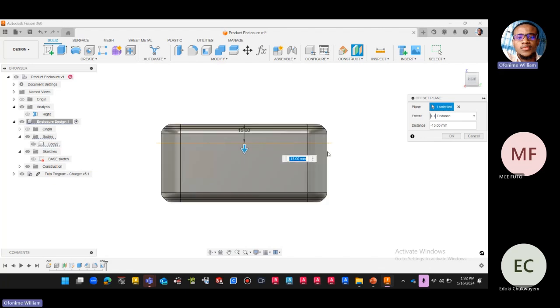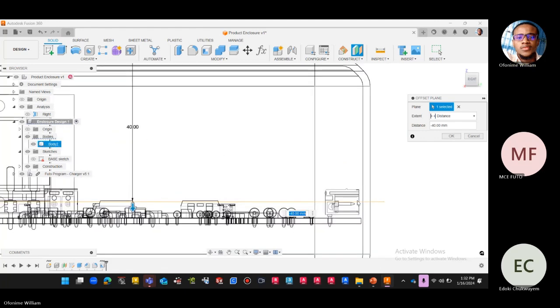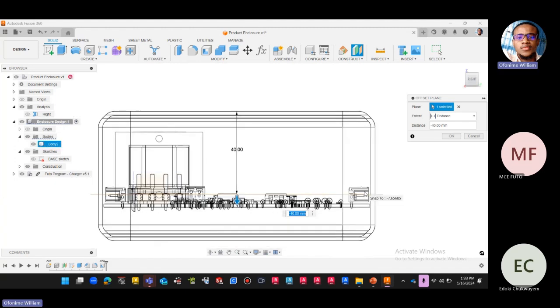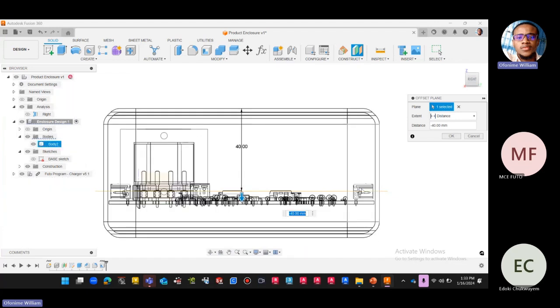Remember I said my plane is my knife, right? Turning this one back to wireframe. It means I could cut this all the way here, but I can't exceed. I will probably want to stay away from this region, right? I'm showing you some thought process now. I probably want to stay away from this region, making this the split point of our case, because it will bring in a lot of complexity, even when you're trying to print. That's one. And secondly, even during the design process.